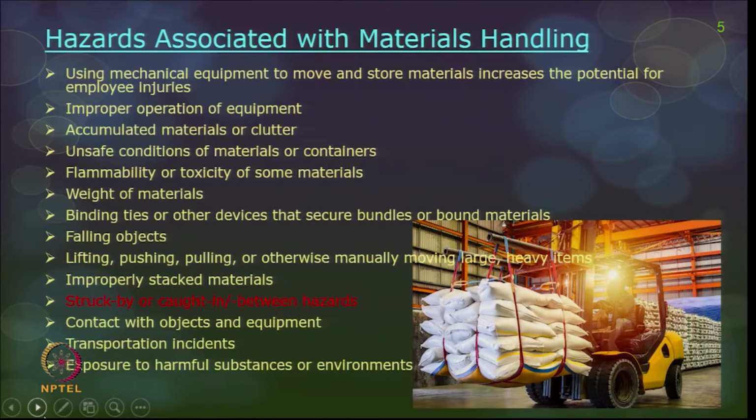As seen in the picture, you should not overload too much material. You should know what is the equipment safe load and what is the safe lifting load of the processes, maybe using slings or maybe the hook. You should know what is the maximum safe load of material that can be handled.